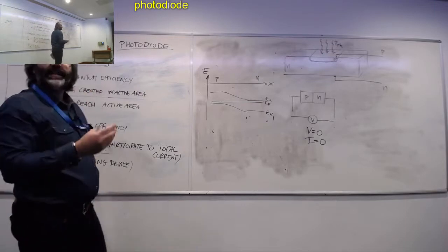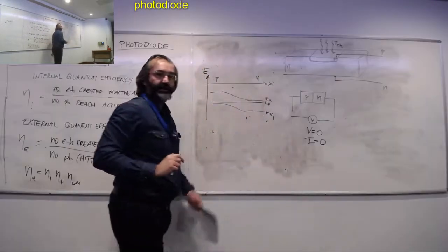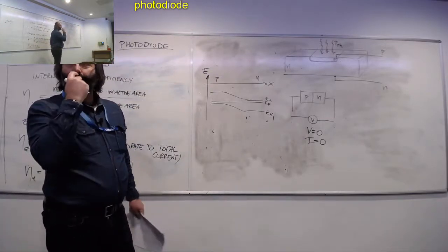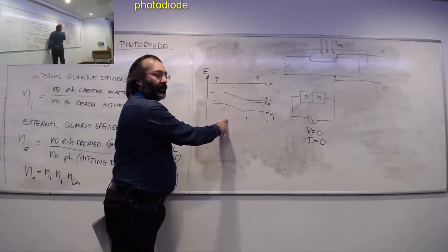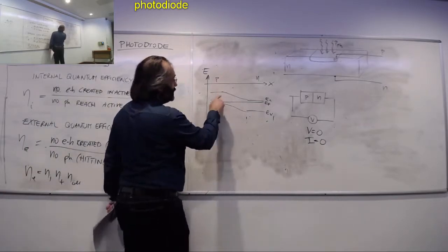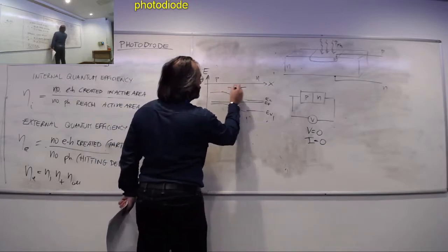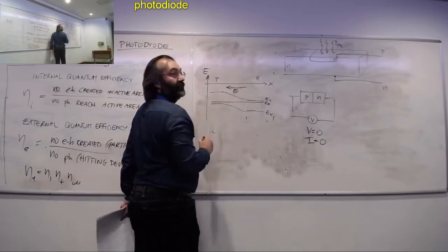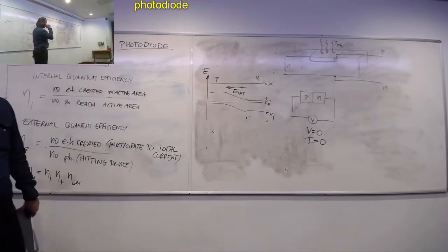So let us now imagine that, still with no voltage applied, I start shining light on this. Now remember the story that this non-flat behavior of the conduction band is telling us that there is an internal or external? Internal. There is an internal electric field.